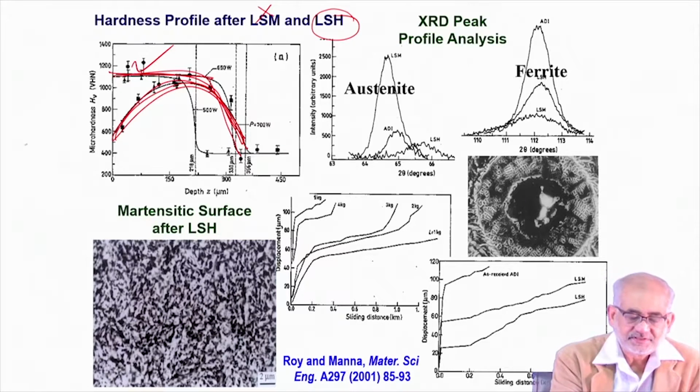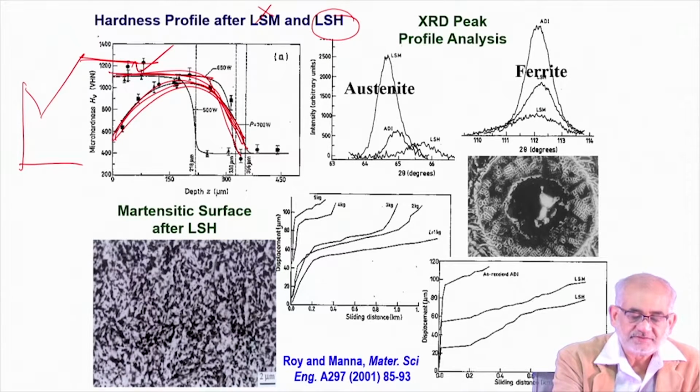In other words, let's say this is the eutectic isotherm, and if this is your composition, if you manage to heat up to this temperature and not go into the semi-solid region, which is the region that will have gamma plus liquid, so liquid may form if you cross this isotherm.